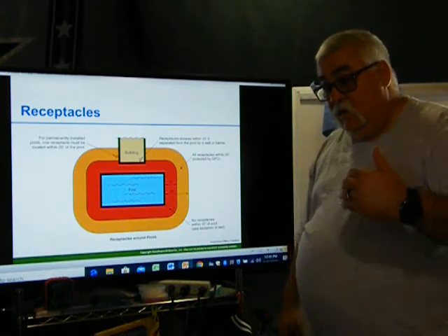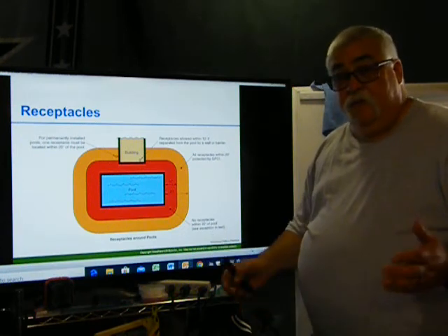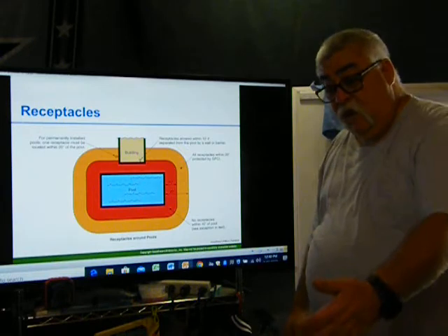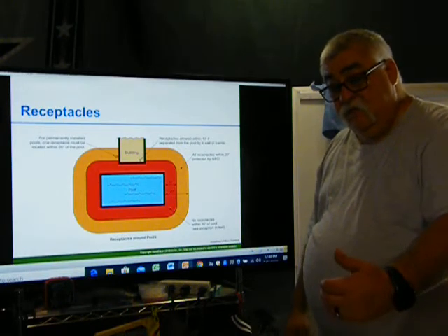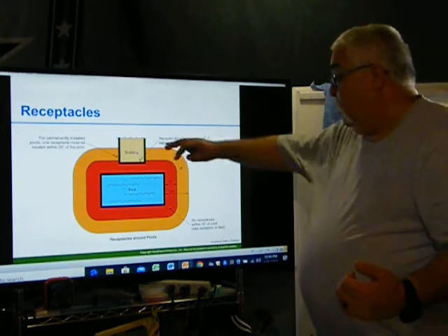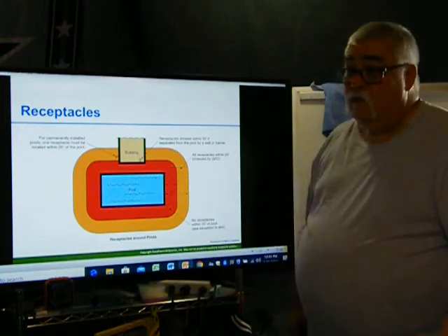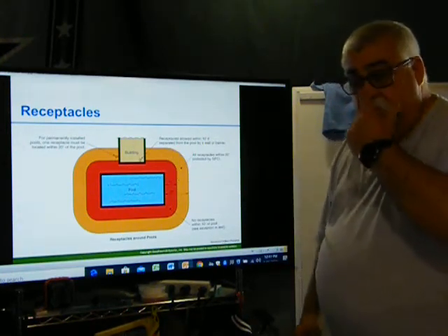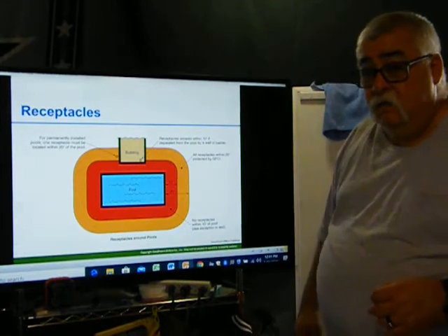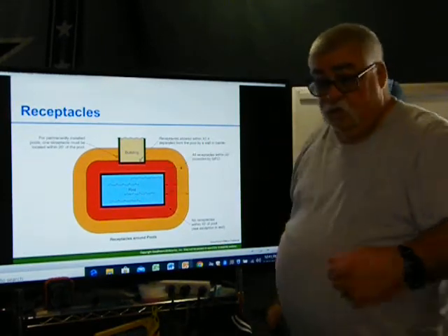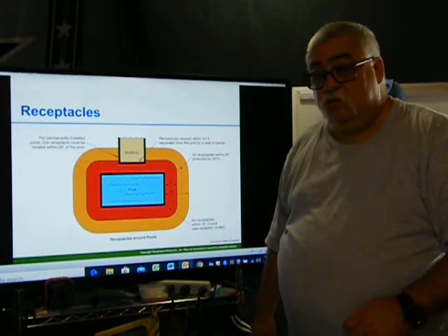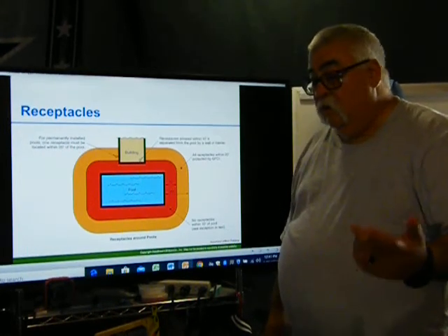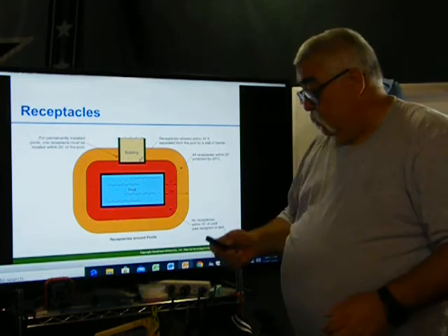A fence, a wrought iron fence that has a 6-inch gap, you know, it's not a barrier. So if you have an outlet right outside that fence, guess what? It's not stopping you. And if it's within 10 feet, then it's a no-no. If it's outside 10 feet, then it's okay. But if it's within 10 feet and it's just a regular GFI duplex receptacle to plug in, you know, your radio, your whatever else, then it's a no-no.